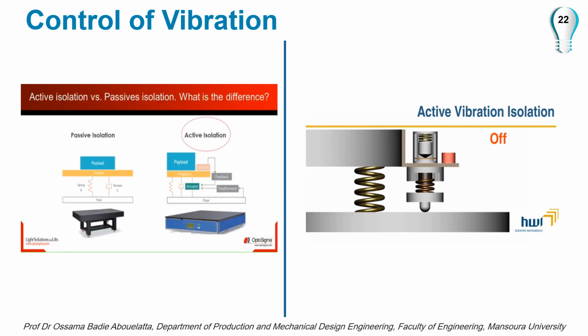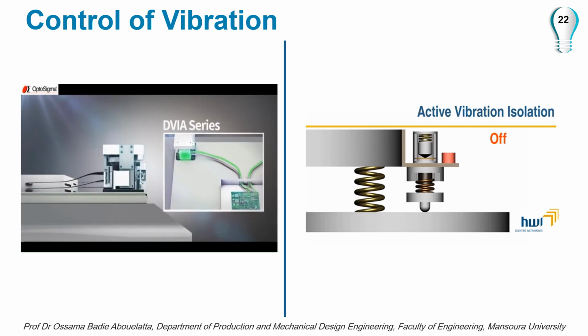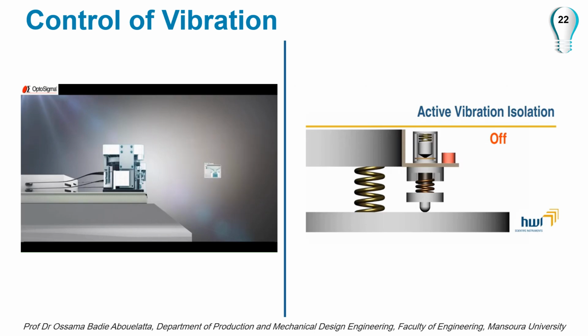Active vibration isolation systems include a feedback system, that is checking the position of the breadboard with integrated digital sensors. Vibrations can be suppressed more precisely and quickly via actuators and the feedback option. These are used for more sensitive optical equipment at low frequencies. For comparison, our human ear can perceive frequencies from 20 Hz to 20 kHz.